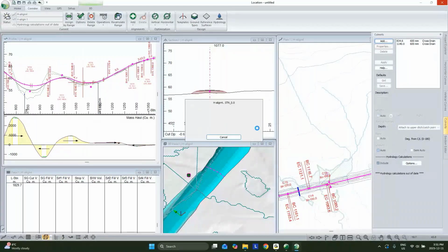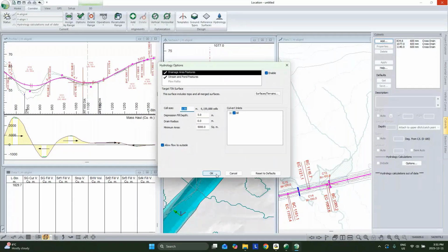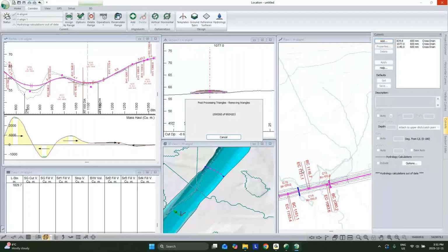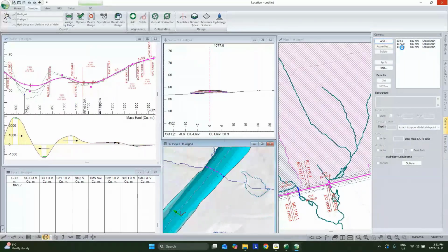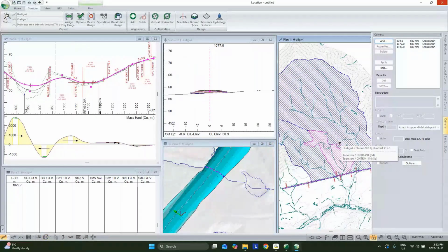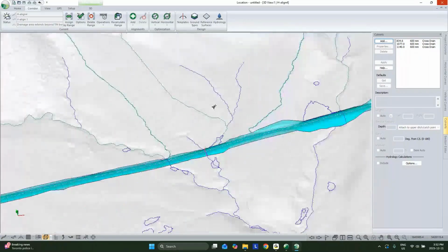So we can quickly add in our pipes, and then we can rerun the hydrology tools and update those numbers as we go. Identify problems, quickly solve them. Pretty easy to work with. So yeah, talked more than I should have there, but didn't want to assume too much to start. But yes, hydrology tools are in location in 12, and they make it really easy to understand how you're interacting with that pre-existing flow regime and the impact your road will have on flow.